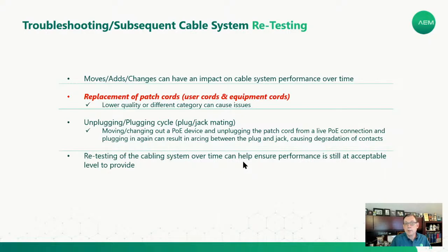So, a lot of times you can use this for troubleshooting, new installations, testing. Moves, adds, and changes can have an impact on your cable performance over time. So it's good to periodically do some retesting, especially if you start to see a problem creep up here and there. It might be good to do some testing. At the very least, do some spot testing throughout the system.